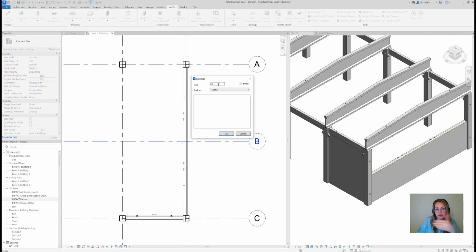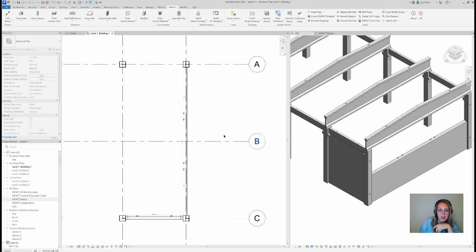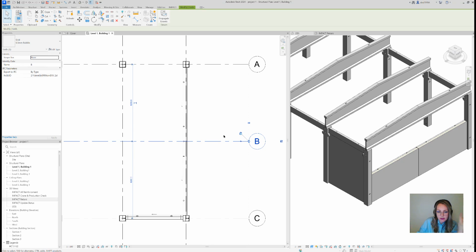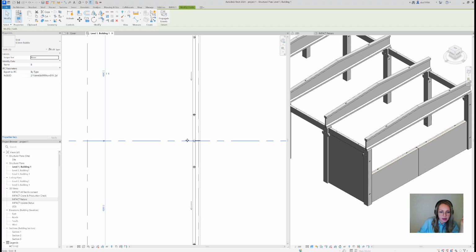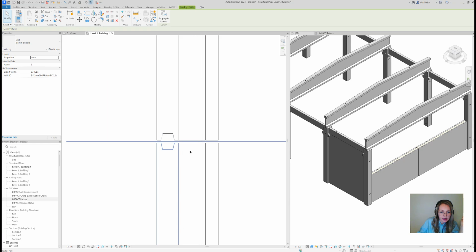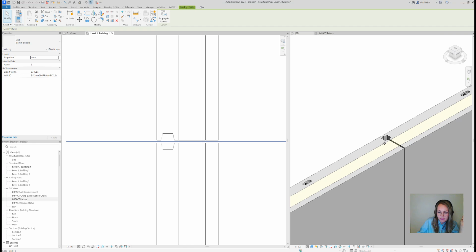Here you can insert the gap between those walls. Let's say we take it as a 16, and pay attention that while doing it, you can actually add an end geometry automatically to these two ends of the wall. So all those end caps that I have in the database, you can go and already use now. Here it is. I split the wall, inserted the gap, and I have my end geometry defined. You can see it in here.